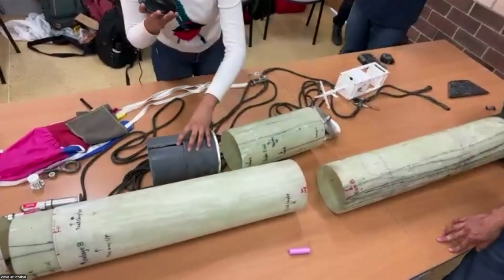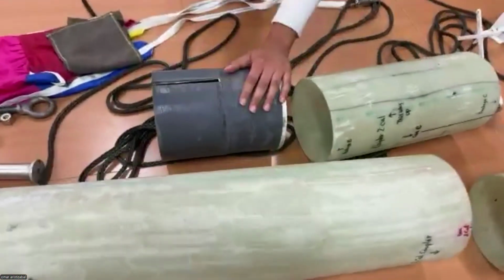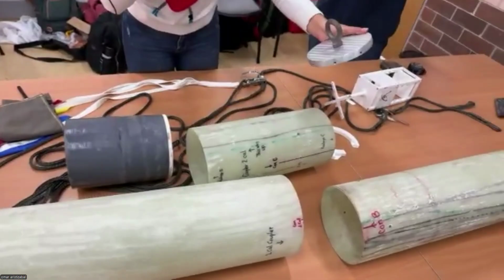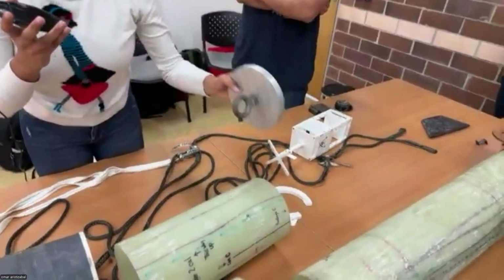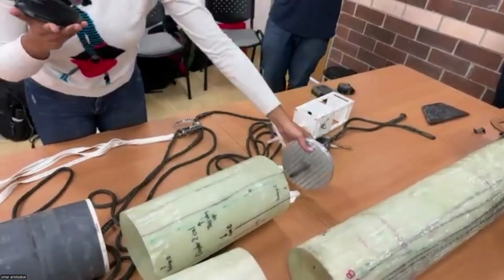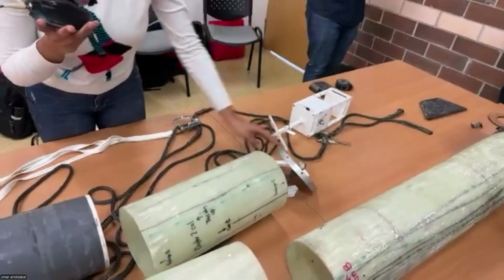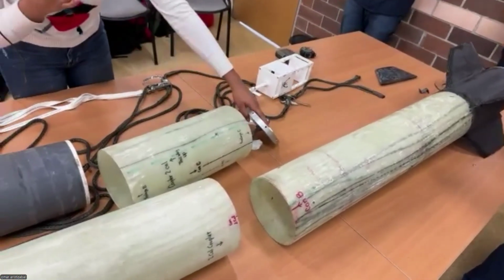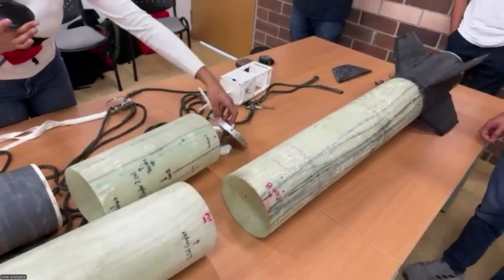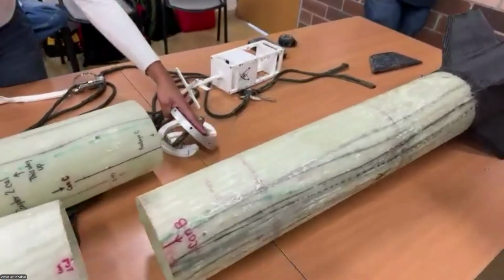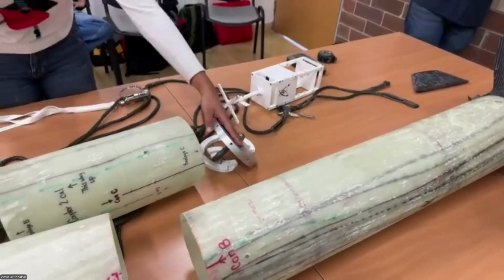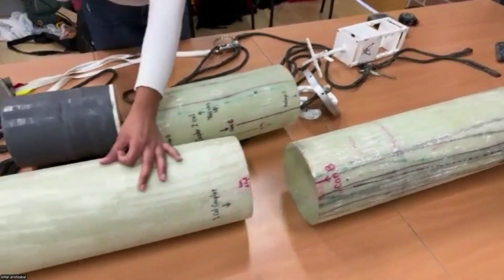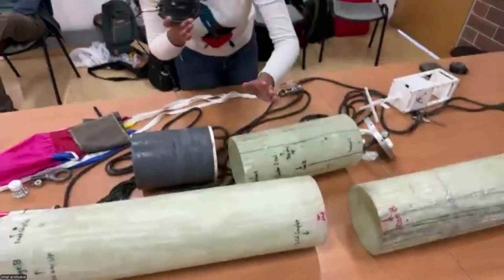Well, that big aluminum bulkhead you have right there, that'd be a really good spot to put a rail button in between 2 of those holes. Yeah, you just have to make sure you use the same alignment every time. We don't really want to touch these bulkheads more, since they were CNC machined and we don't want to mess them up. But we will reinforce the spots where we put the rail buttons with fiberglass layers.